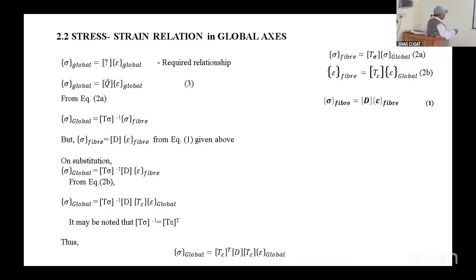So it may be, incidentally, a symmetric matrix. What is the principle of continuum mechanics entering into the equation? Continuum mechanics means if I apply a force here, what is the displacement I am getting there? I will get the same displacement here if I apply the same force. This is the reciprocal law, when the medium is continuum.